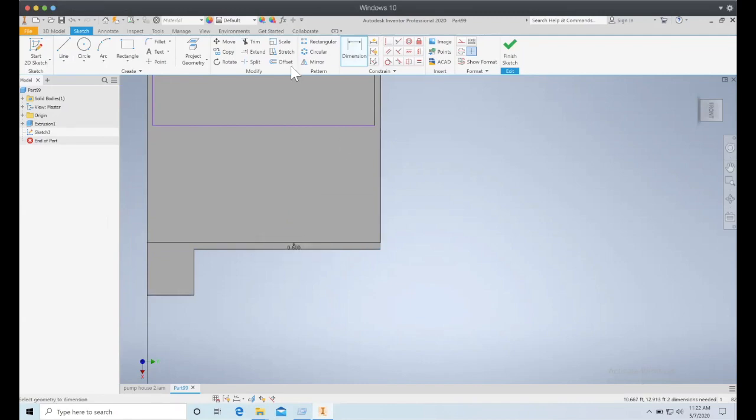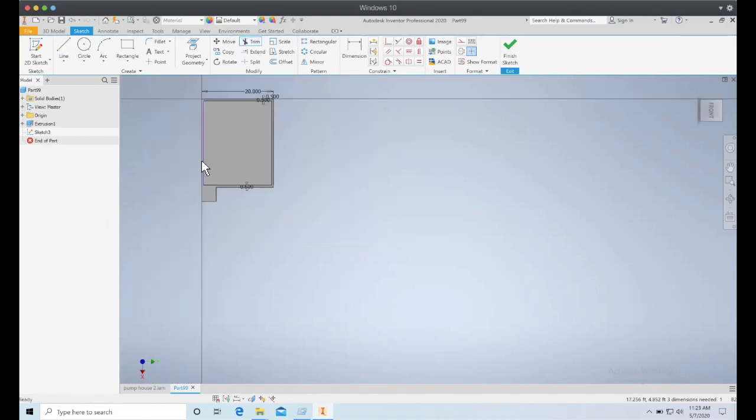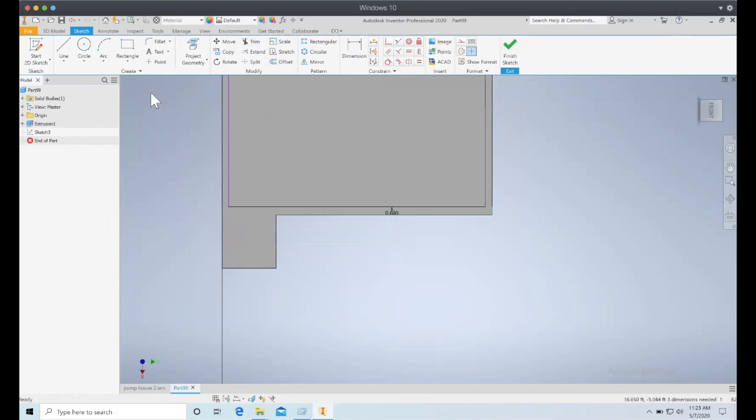All right. Now I will demonstrate another very cool tool, and I'm going to extend a line through. Click Escape. And now we have some extra lines here, so I'm going to trim that off using the trim command, and also trim this as well. We're almost there. Now I'll go to my rectangle tool and snap onto the edge there.